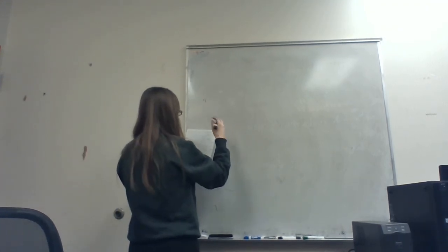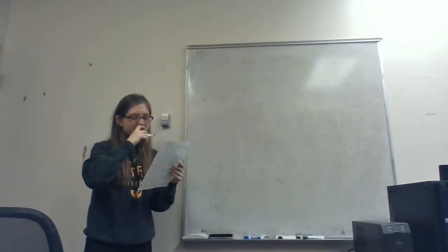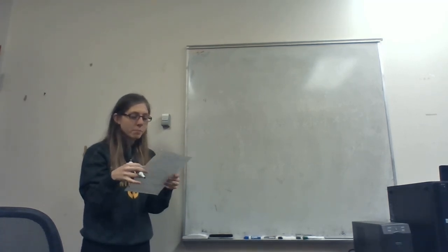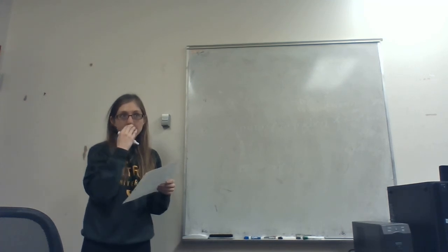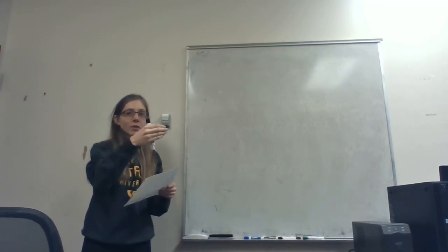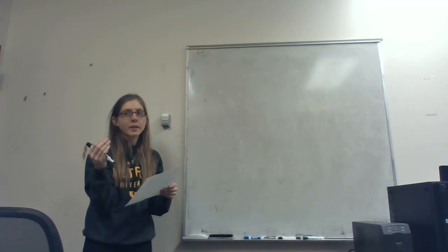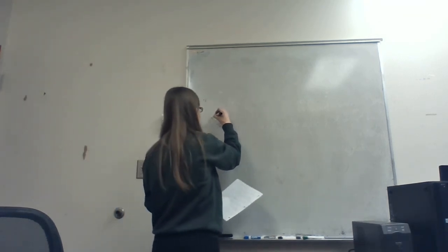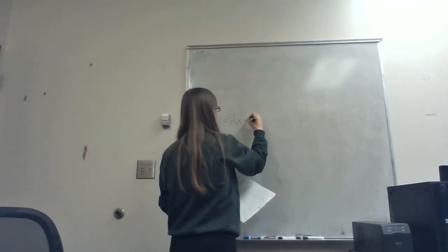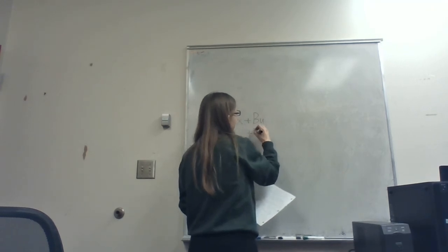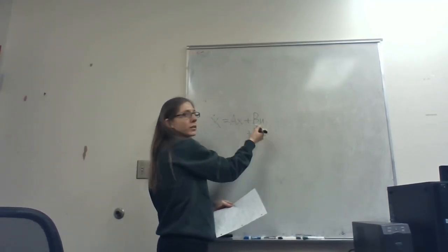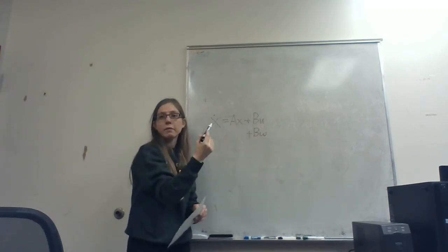there can be cases where, for linear systems, when the eigenvalues are negative or the poles are negative, we have a bounded input, bounded state type of stability, where you give it a bounded input and what you get back is a state that remained bounded. That would also mean a bounded disturbance, taking a similar rule to the input. So x dot equals ax plus bu, or plus bw, for example. You give a bounded value here, you get a bounded state if your eigenvalues are negative.